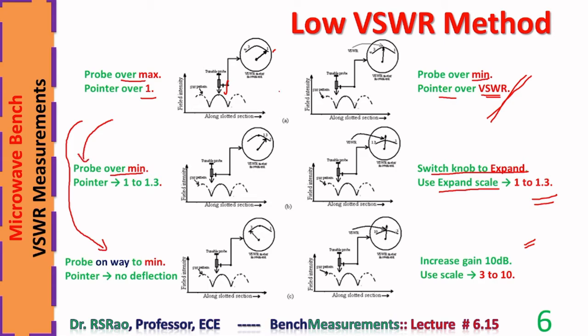In the first step, while you are moving the probe to minimum, when the probe is on the way to minimum, the pointer may fall to no deflection position. It may be somewhere here. You have not yet reached minimum; you are between maximum and minimum. The pointer shows no deflection. Then what to do? Increase the gain by 10 dB. When you increase the gain, the pointer may acquire some deflection, let us say something like this.